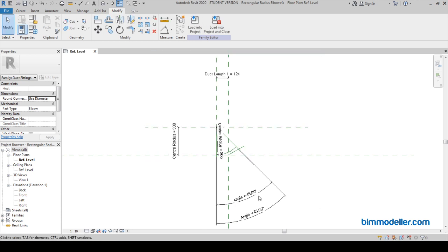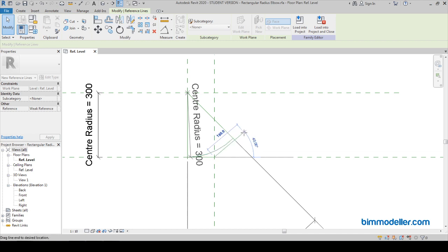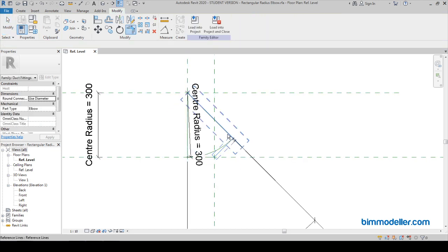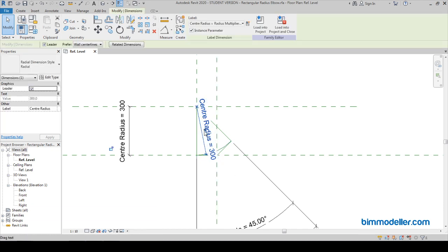Say OK. Now if you see the 45-degree, you can assign an angle constraint to this line also, but it isn't required. You can directly connect with this line, so automatically it will be locked with this line. Whenever you do constraints, I'm doing a hatch to hide this dimension, or you can move it away from this position.